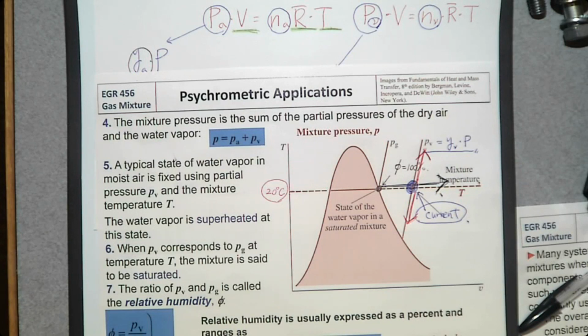Why is that? This is the cabin temperature. This is the temperature of the air in the cabin. However, the windshield is going to be at a lower temperature than the air in the cabin because the outside is cold, right? So the air near the windshield is going to be at a lower temperature than 20 degrees Celsius. What about the windshield being sub-zero, somewhere down here?